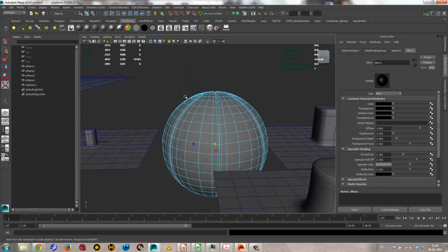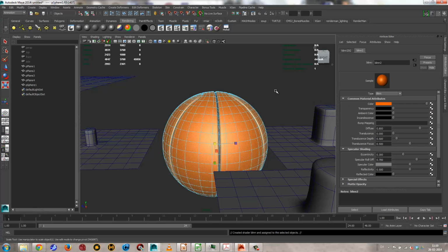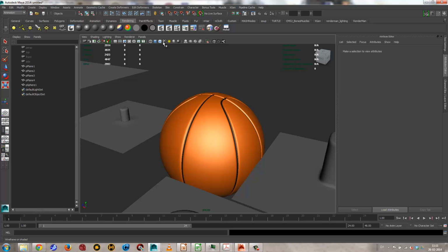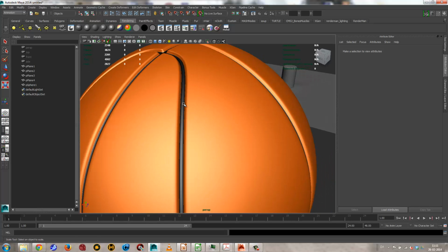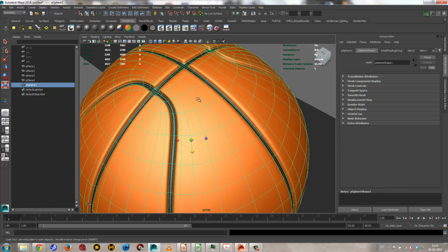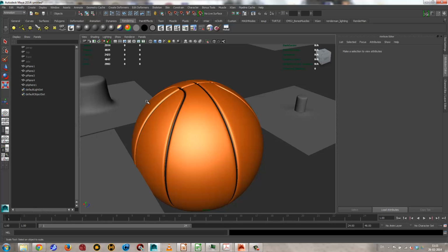And then if I hold shift, I will toggle select the whole model, and then the other part I will make that orange. Something like that. So you can see it's fairly quick, but the thing is, doing this without edge loops would take forever. The idea here, the real trick, is when I create the original sphere and I remove the edges at the top and the bottom and then realign them so that I'm able to create this flow going around this area here.